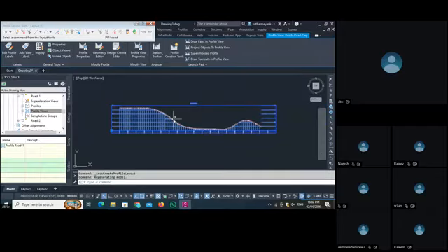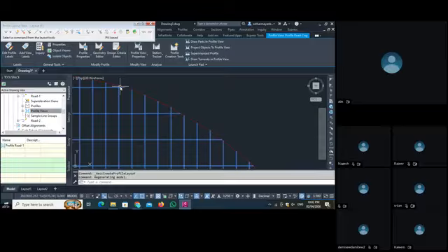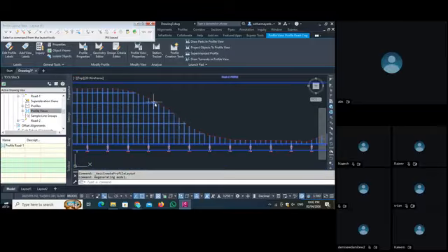So now this red line is the surface profile. Before providing our profile view, first we add the surface in the profile. For alignment 2, where our alignment 2 is on the profile, they will take that part as a surface profile here. Now what we are doing as a design profile, we set a smoother road, because you see here this profile is created on the surface.